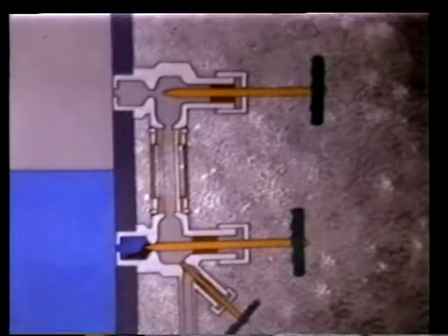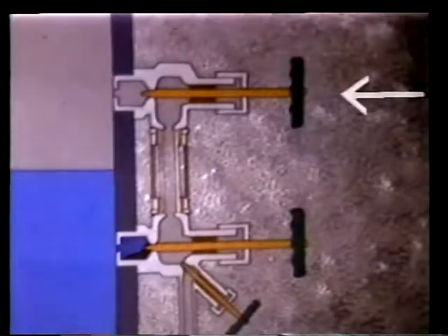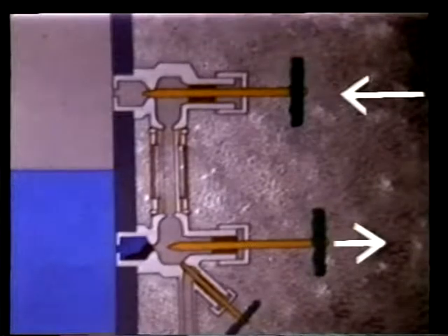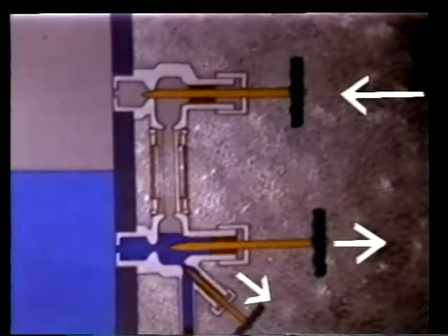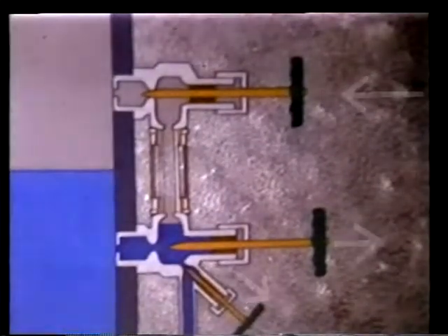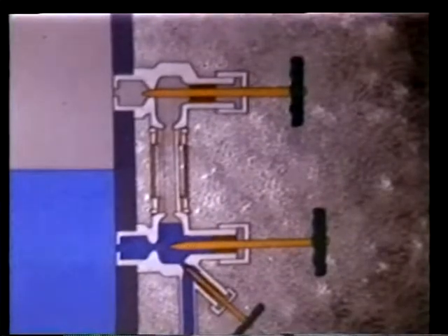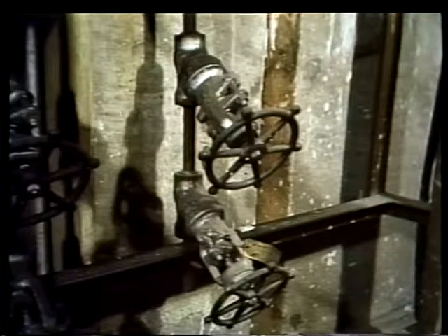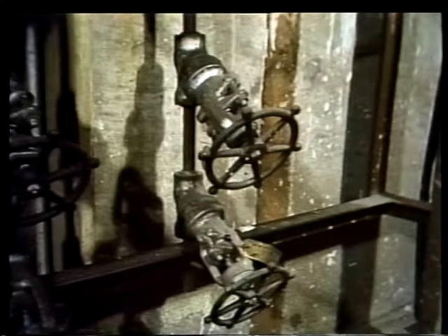Do the same things to the lower connection. Close the upper valve and open the lower valve. Then partially open the drain and blow down until fluid flows easily from it. There may be two drain valves in series on a high pressure gauge. Both of these must be opened in order to blow the gauge down.